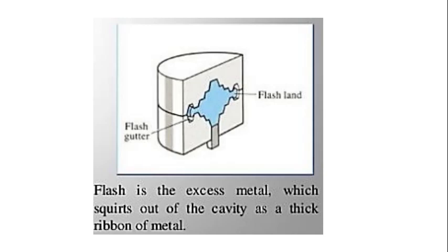Okay, we will provide some excess metal so that there will not be any empty spaces and your cavity will be full. So it will work as a cushion during the forging. Since we are providing some extra excess metal, we have to provide some space for that metal in the die itself. That extra metal is called flash, and that extra space in your die is called gutter. Okay, these two terms you should remember. Sometimes they ask questions on what is flash, what is gutter.